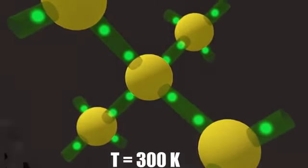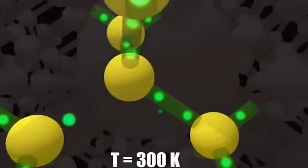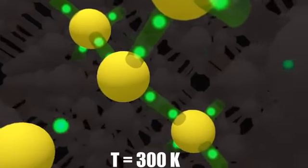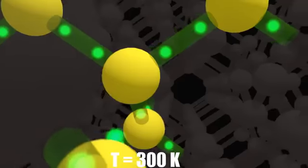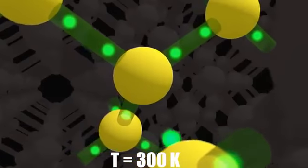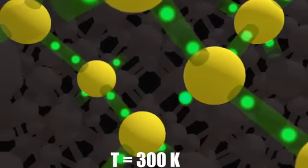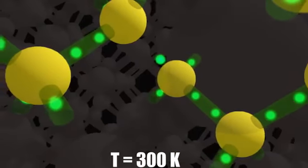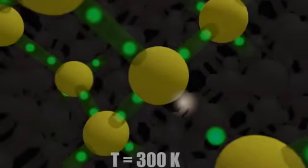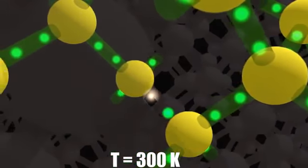When the temperature rises, some of the electrons in the bonds are able to gain thermal energy and escape. They are now free to move and to conduct electricity. At the same time, the broken bonds can be occupied by electrons from other bonds. For these electrons to move, no additional energy is required on average. This broken bond or new state is termed a hole and behaves as a particle of positive charge and mass.